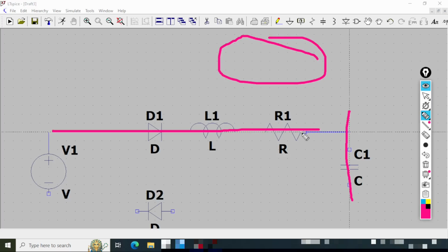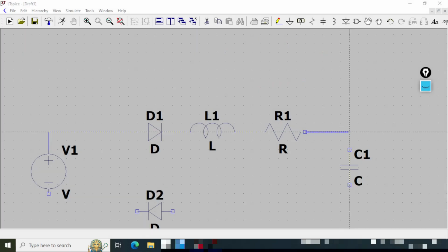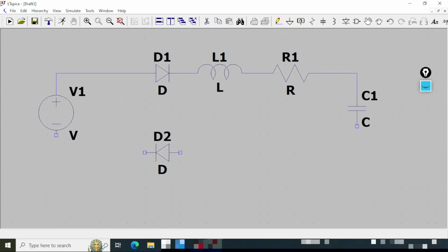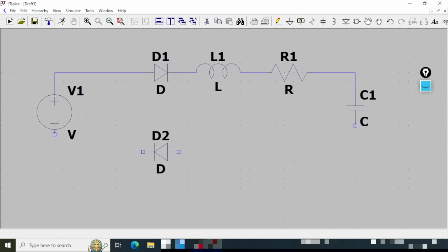So basically this crosshair snaps with the grid, and you can now come down and connect these things. Let me come here at this point, click, and then I connect. All these clicks are single clicks. There is no double click in the wiring. So I will hit the escape button, deselect anything from the keyboard, and I will click and drag the circuit upward so that I have some space for the wiring for the bottom part.